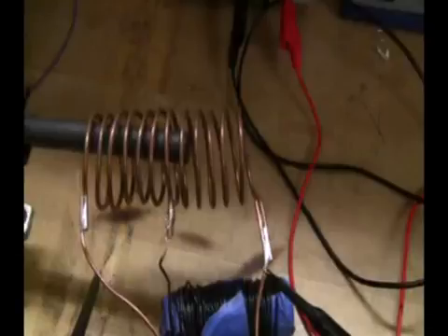The resonant frequency of the system is also a factor in the heating of objects. The faster that the current alternates, the closer the current density in a material pushes towards the surface and away from the center. This is called the skin effect. In doing so, the effective resistance of the material increases and causes more joule heating in the object.